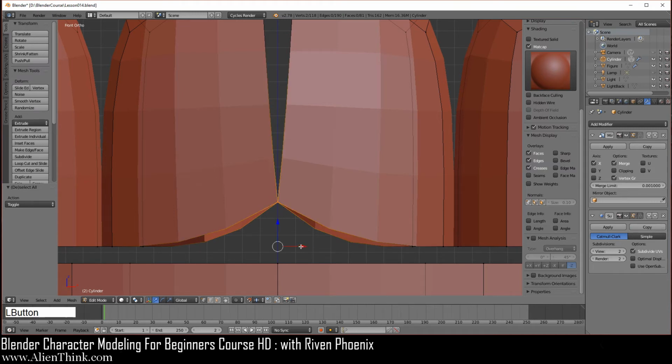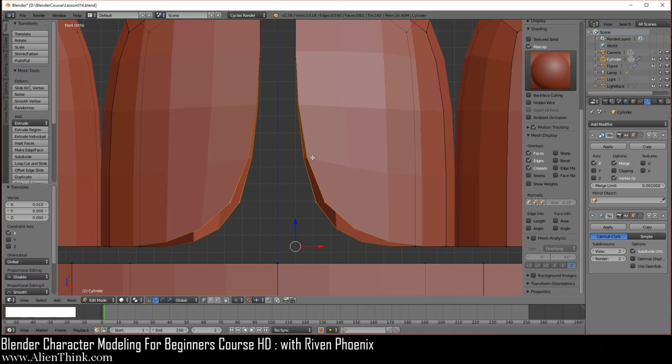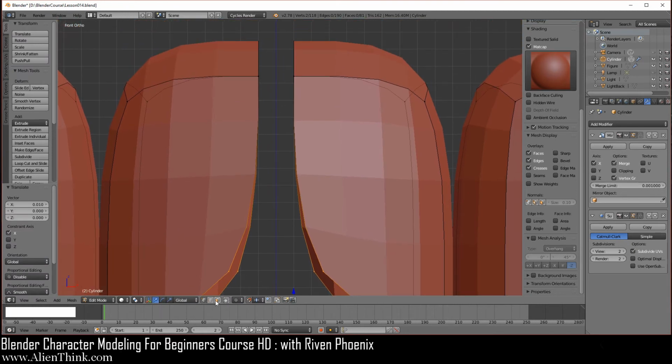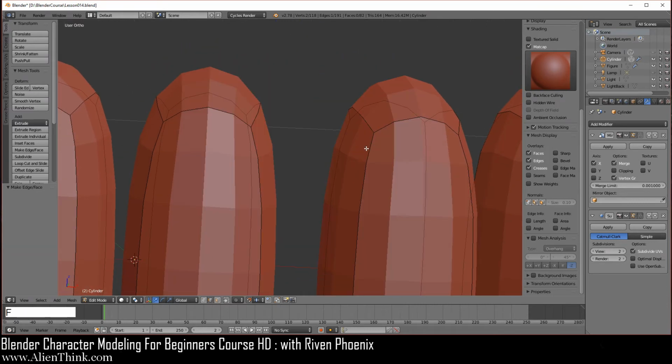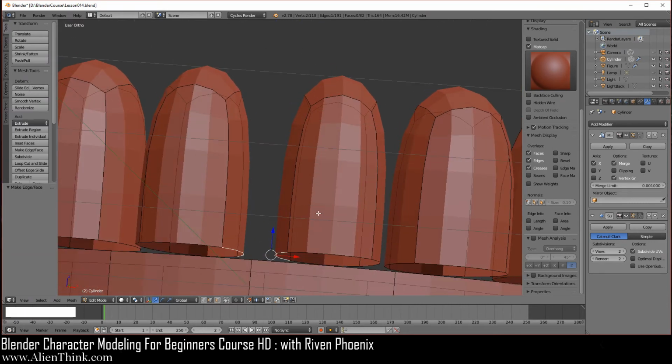You're going to take the red arrow to the right to separate this. Then Shift and middle mouse button, just pan over here, click on the edges, click on this edge over here that I did, now do F. So what I'll do is put it over here. Now you're going to click on the face select mode. You can click this off over here, okay?